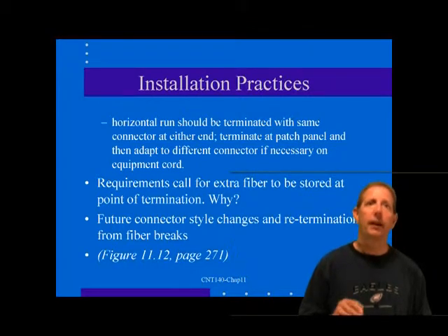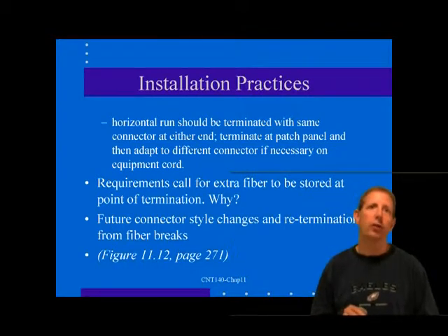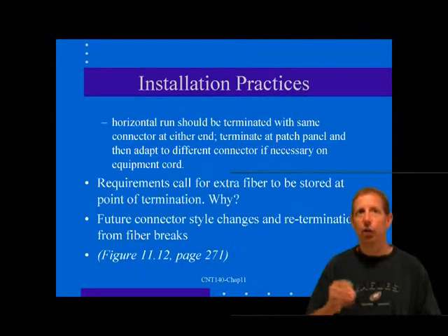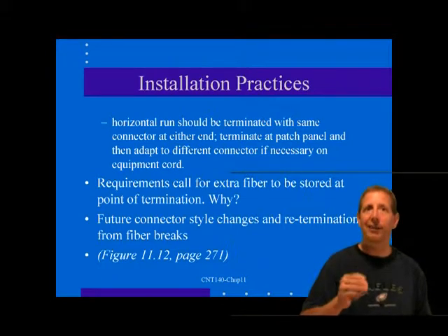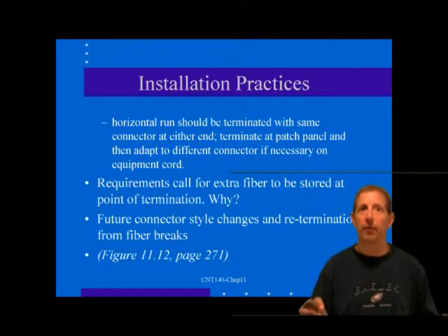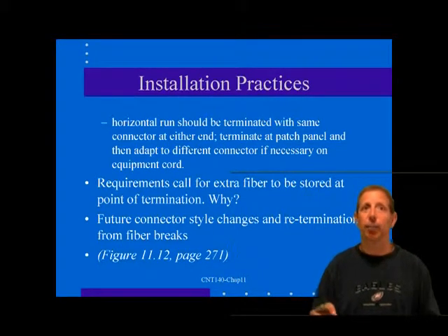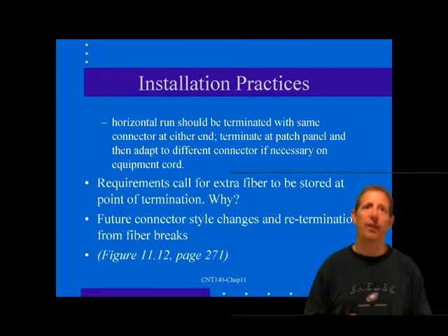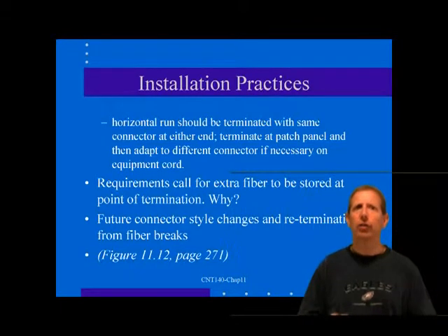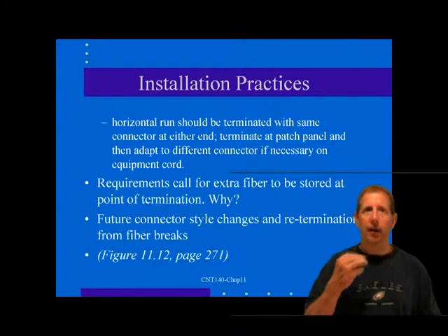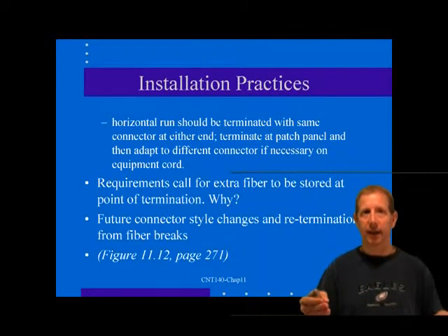of time. The fiber is now trimmed to the proper length, usually with a tool that purposely scores, or nicks, the fiber and then breaks the unwanted portion away from the remaining fiber. The breaking process is called cleaving the fiber, and it should leave an orthogonal break at the fiber end.